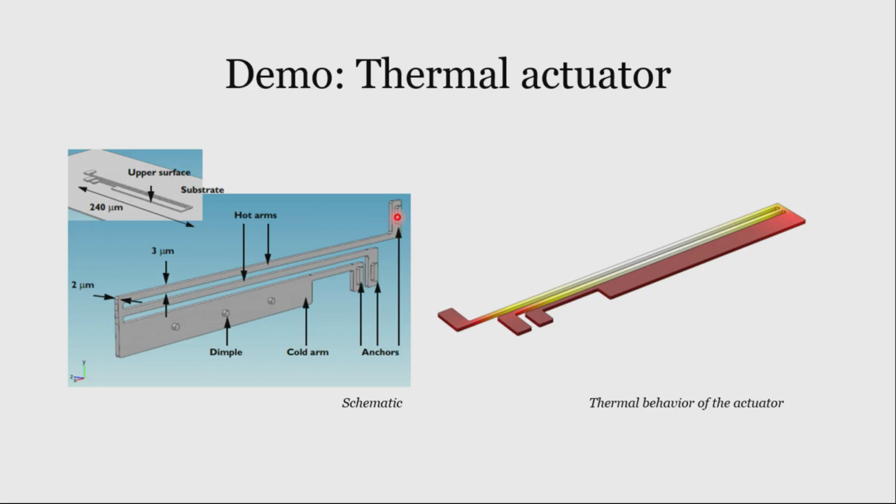So the voltage that we give over here is through anchors that you can see over here. These are the 3 anchors, and based upon the current that is flowing through the space. If you confine the space of the flow of current, it actually creates more heat energy as compared to a space which is not confined, right. So over here you can see that the space is very much confined. You need to give a voltage over here and you ground these particular anchors. So top anchor you give a particular voltage and you ground the bottom 2 anchors.